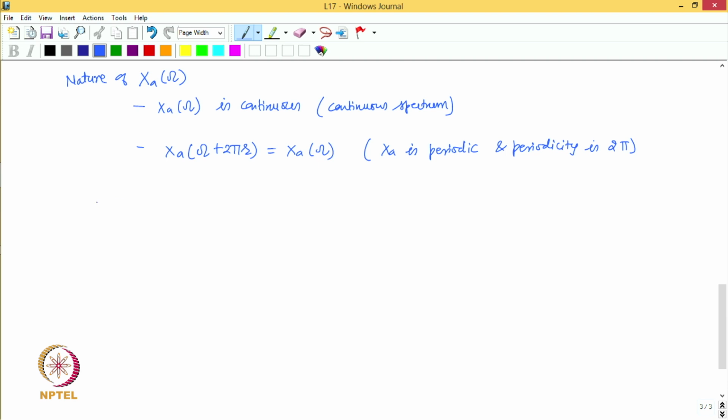Now, we can also obtain the spectrum in terms of radian per second, right, that is if the frequency axis has to be in radian per second, then we can obtain this by simply dividing this by delta t. So, by dividing x a uppercase omega by delta t, we get the spectrum in terms of radian per second, just a scaling factor. So, now for the pulse signal, right, that aperiodic discrete pulse signal, let us try to sketch what the DTFT or the Fourier transform is going to look like, right. So, let us do that.